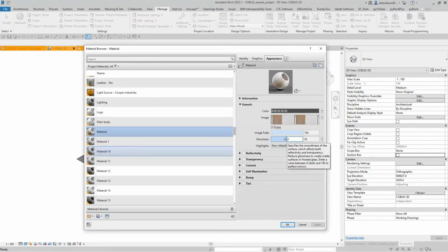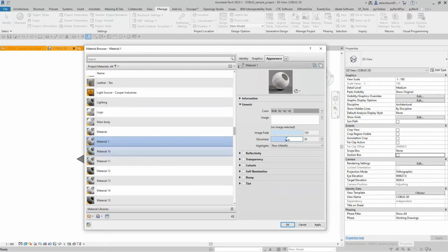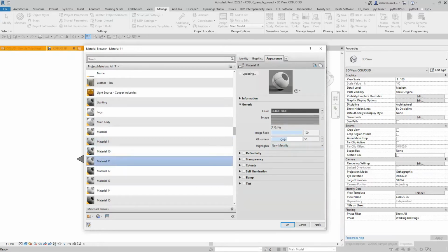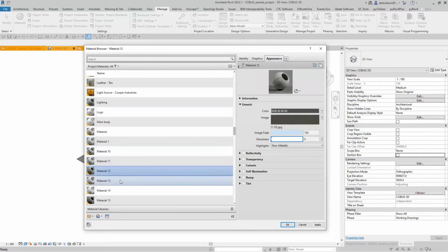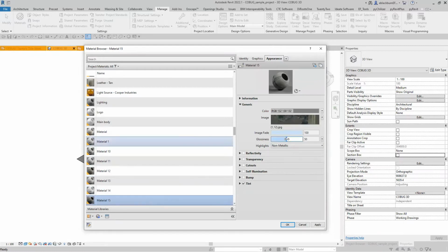And you'll notice that it's set to a glossiness of 50. So it literally entails coming in here and adjusting all these down to a glossiness of 0. So it doesn't get the reflections. And unfortunately, the bigger the site, the more materials there typically are, because it sections up the imagery into little parcels.